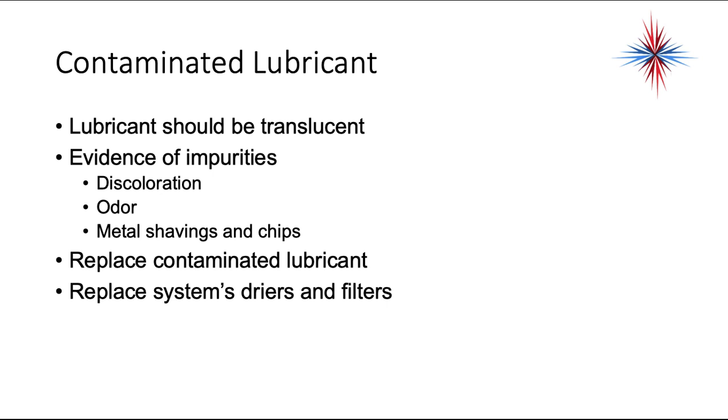Lubricant should be translucent. Evidence of impurities in lubricants is discoloration, odor, metal shavings and chips. You want to make sure you replace contaminated lubricant, and you want to replace system dryers and filters.